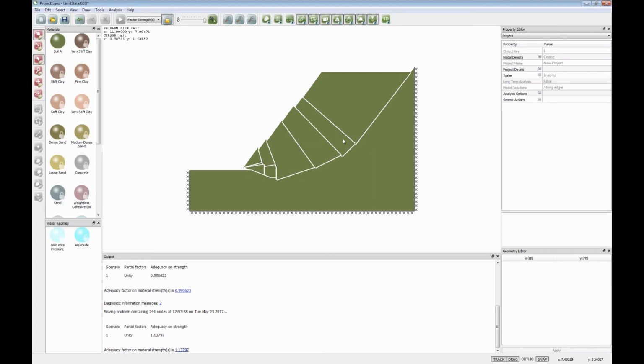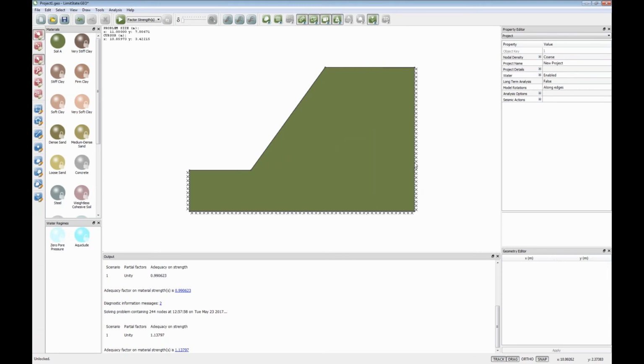The problem with this analysis is, one thing to watch out for is if these boundaries, so this one on the left, is not a real boundary, it's just an artificial boundary. Unless there's really rigid rock there, this is not going to happen, and this mechanism is actually intersecting the boundary, so it's not fully accurate. So really I should move that boundary sideways.